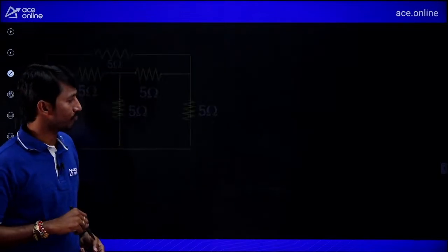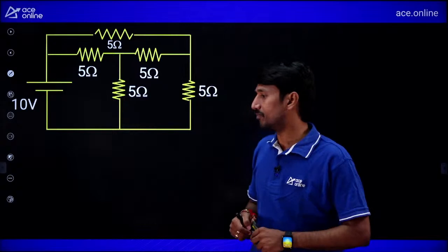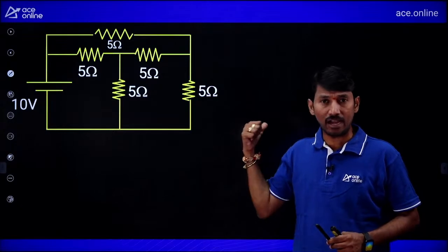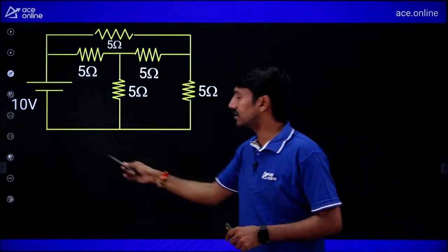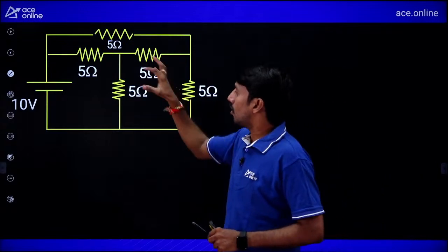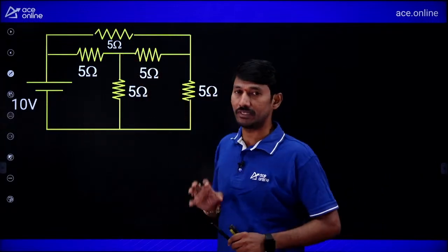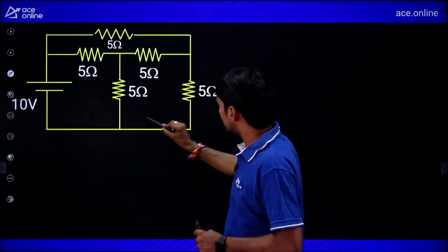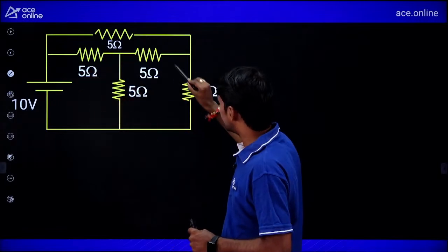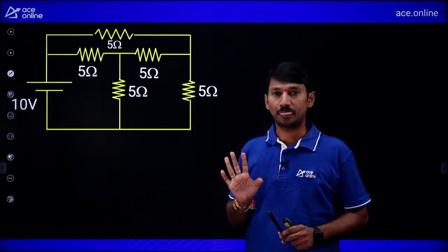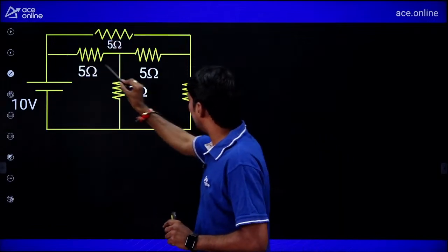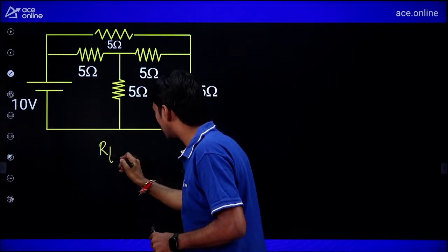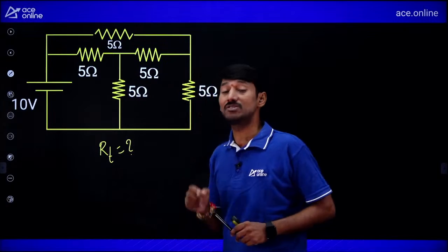And one more question. Suppose, let me take network theory. So far I have taken one subject, machines, as an example, and EDC, analog electronics, as one example. Now, suppose this is network theory. If you want to simplify this network, different methods are there. Sir, one is star connection, this is star converted into delta, or this is delta converted into star. You can simplify, you can find out R total, but that is a very lengthy topic.